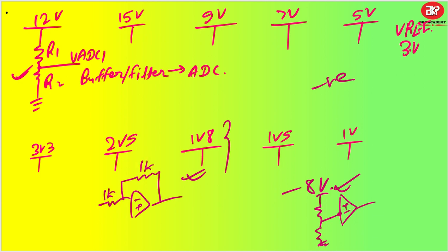You can keep it lower also, and then this will be the voltage input for your negative voltage, and this will be ground. Whatever V out comes goes to your ADC. So this is how you have inverted your input so that it becomes positive, and then send it to your ADCs. Understood? Alright, so these were some of the occasions.